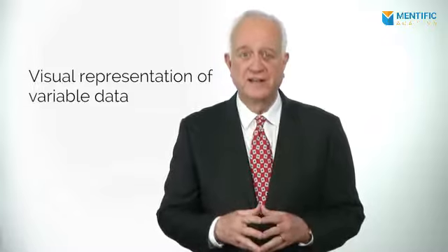The next basic quality tool that we will discuss is the histogram. Let me describe what a histogram is and the information it shares. A histogram is a visual representation of variable data. It organizes data to describe process performance and displays centering of the data and the pattern of variation. It demonstrates the underlying distribution of the data. A histogram can be used to check whether or not the data is normally distributed. It provides valuable information for predicting the future process performance. And it helps to identify whether the process is capable of meeting process requirements.